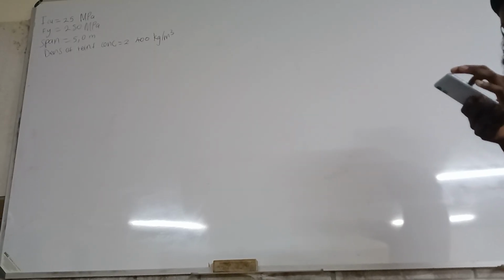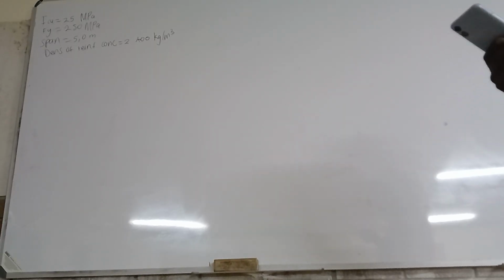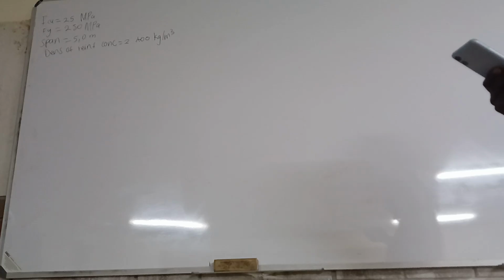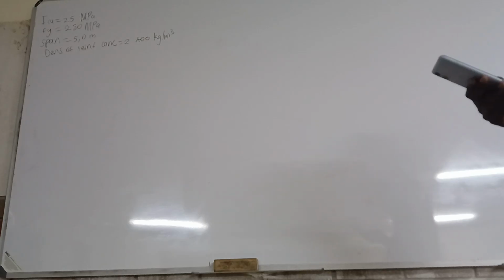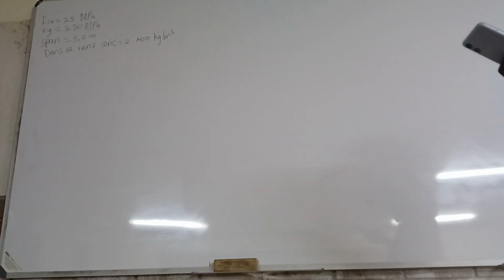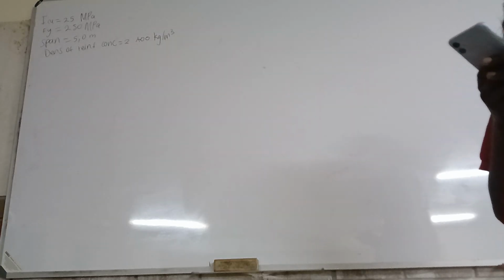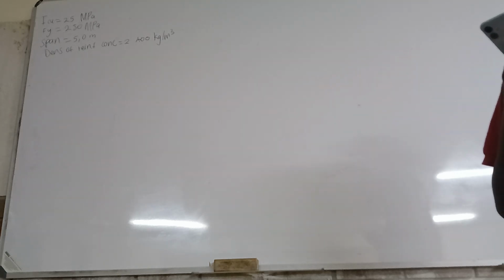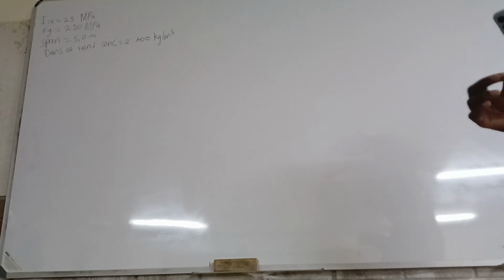2020 April question 1. A simply supported reinforced concrete beam has an effective span of 5,000 millimeters. The width of the beam is 220 millimeters. The RC beam must support a 16 kilonewton mid-span point load and a 7 kilonewton per meter uniformly distributed load over the entire span. Use the following information to determine the required reinforcement to withstand the loads.